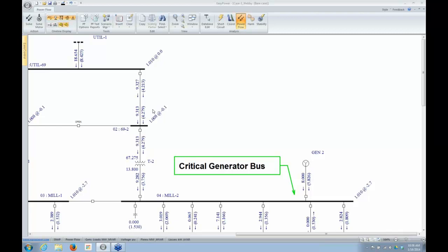Can you choose a portion of the whole model and run a power flow? No. So you could deactivate parts of the system and run it that way, but basically the power flow is kind of all or nothing. I cannot run power flow on a part of an energized system. I would have to configure it in a scenario and maybe deactivate part of the system. I could do it that way. The switch is only open when it says open. Yes, the default is that all the switches and breakers are assumed to be closed unless they say open. That closed is the default.